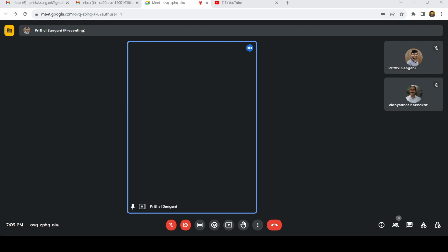So the reaction forces will be, this is one reaction force, and this is the other one. So 30 times 8 plus 34.6 times 8 divided by 16, that is 32.3. Is it? I think I made a mistake in taking the length of the beam.